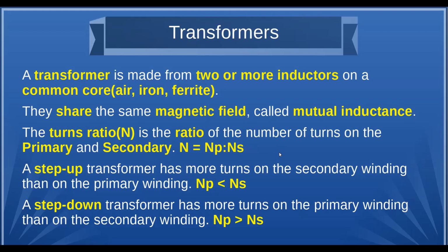If you had a 1-to-1 transformer, which you were just using for isolation, and a lot of times you'll see that in AC utility power used to isolate grounds, it'll have a 1-to-1 turns ratio. So the same number of windings on both sides. There's no voltage increase or decrease.